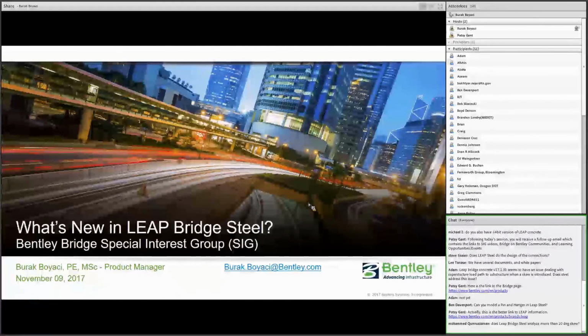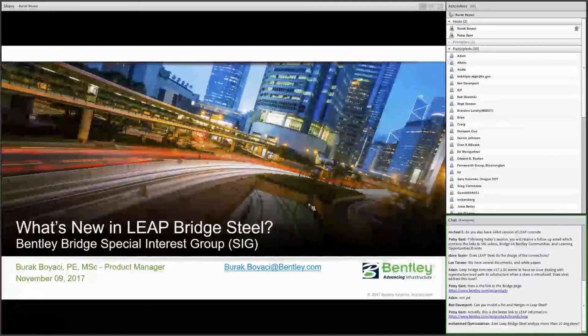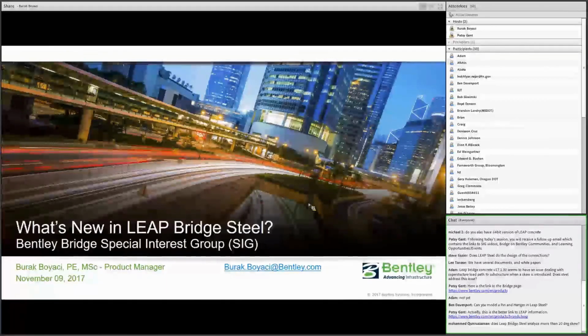Okay, there's a good question from Mohammed. He's asking if LEAP Bridge Steel analyzes more than 20 degrees skew. The answer to that is yes. You can introduce any skew degrees for the support as you want. You can select grillage analysis or FEM analysis for any type of bridge skew. Okay, I guess there's one more question.